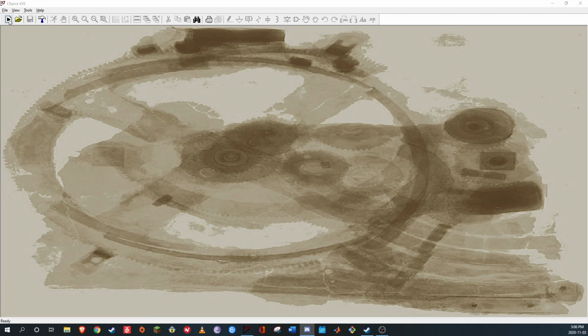So once you have LTSpice open, if you want to start creating, you click on this little button for a new schematic. Could you show me again? I didn't see that. Right up here in the left-hand corner, it looks like a play button. Oh, yeah. Yep, new schematic right there. And then you'll see you've got a whole bunch of options up here at the top.